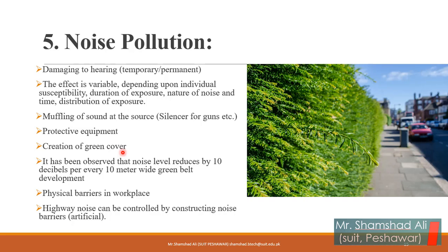Creation of green cover, as you can see here in this picture. It has been observed that the noise level is reduced by 10 decibels, the unit of noise, for every 10-meter wide green belt developed. When you develop a 10-meter wide green belt, it can reduce the noise level by 10 decibels.